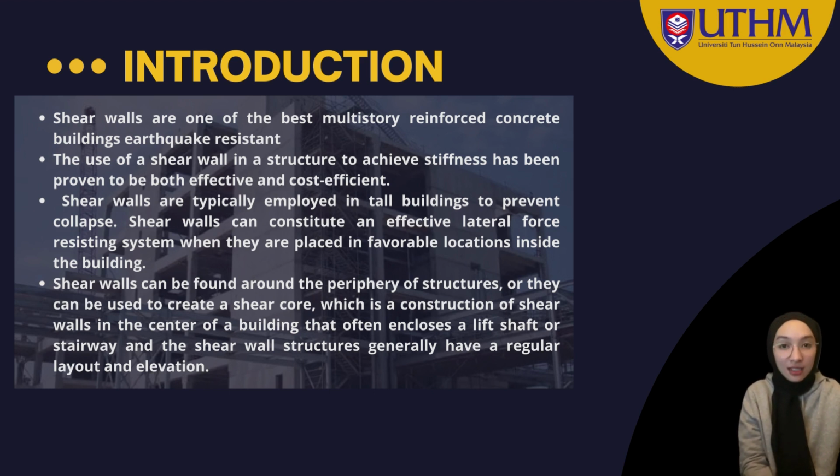So, for the introduction, did you know a shear wall is a structural member in a reinforced concrete frame structure to resist lateral forces such as wind forces? Shear walls are generally used in high-rise buildings subject to lateral wind and seismic forces. In a reinforced concrete frame structure, the effect of wind forces increases in significance as the structure increases in height. Codes of practice impose limits on horizontal movement or sway.